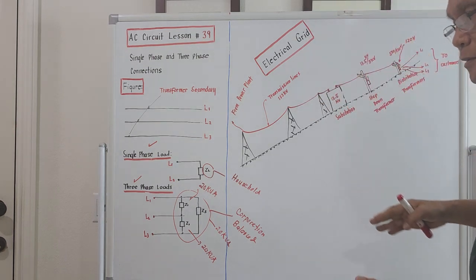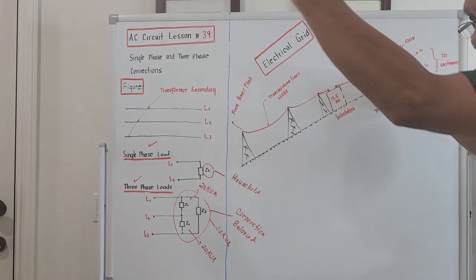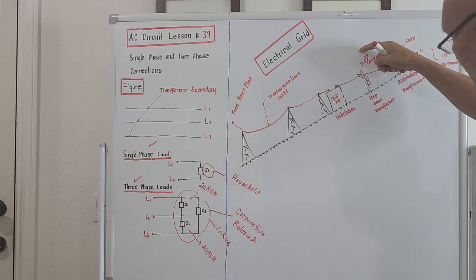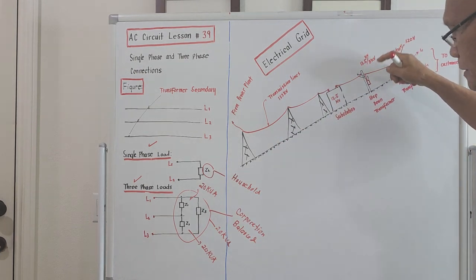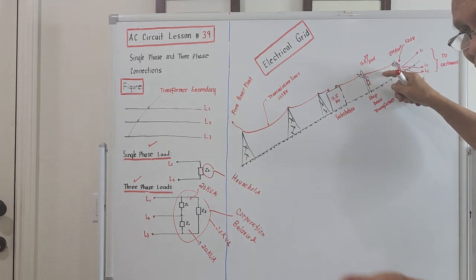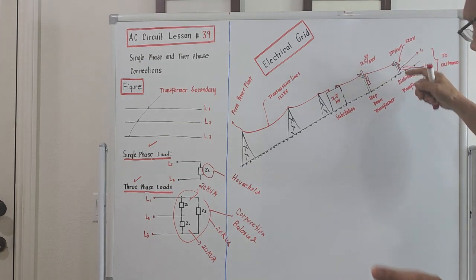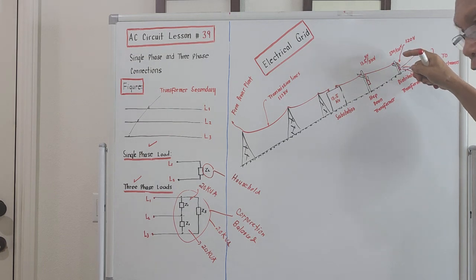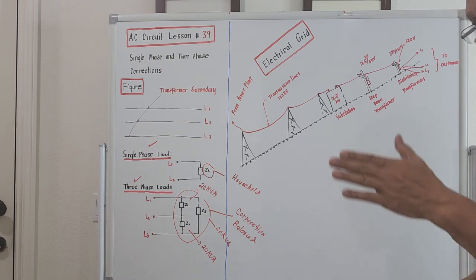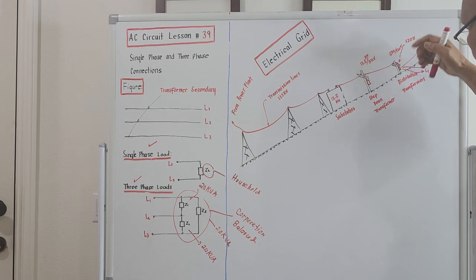it will go to another post which is around 40 feet. It is considered still a primary line, and the voltage hanging over there will go to a step-down transformer that will convert that 13.5 kV to around 5 kV. Then this is connected still to the secondary lines. This portion here are secondary lines going to the small post. And on the small post, there should be again a distribution transformer, which will convert that 5,000 to a usable 120 volts.